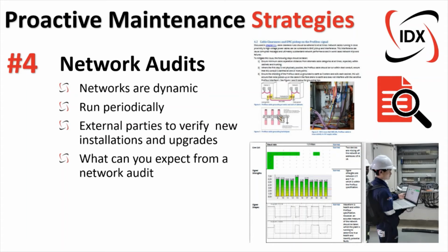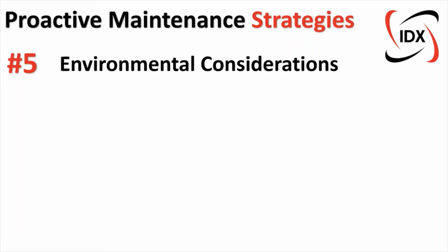And then eventually the engineers should actually connect in some bus monitors and testing tools. Have a look at that nice square waveform I was talking about in the previous slide, and make sure that the network has a very healthy appearance to it. At which point you should get a full report, and the report can indicate any potential risks that need to be corrected on the network, or indicate what the network looked like in that snapshot in time.